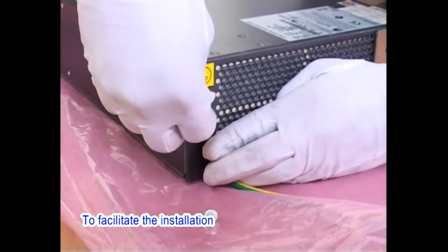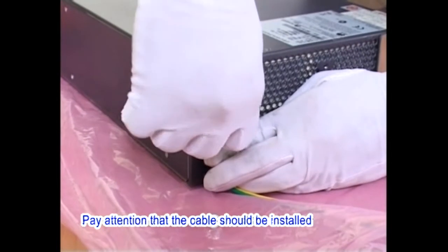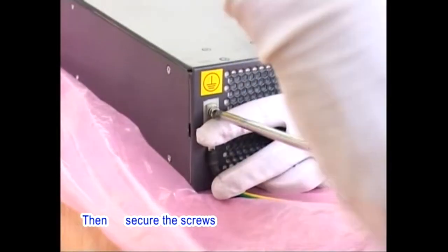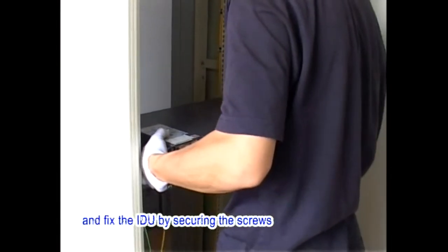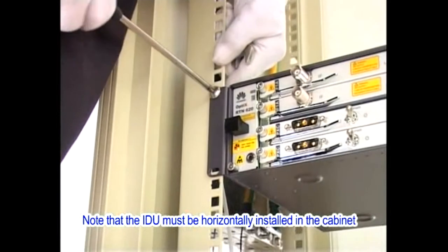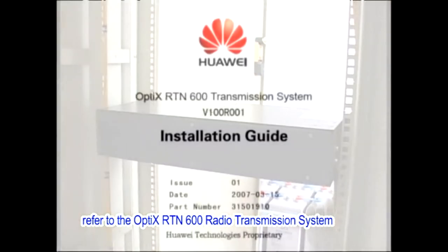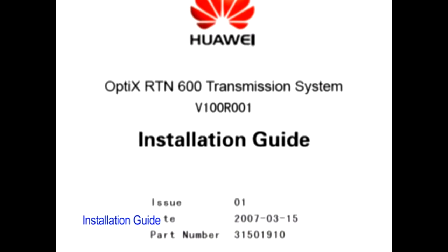To facilitate the installation, you can first install the protection grounding cable to the IDU. Pay attention that the cable should be installed in the same direction as the later cabling direction. Then, secure the screws. Fit the IDU in the expected position of the cabinet and fix the IDU by securing the screws. Note that the IDU must be horizontally installed in the cabinet. For other methods of installing the IDU, refer to the Optics RTN 600 Radio Transmission System Installation Guide.